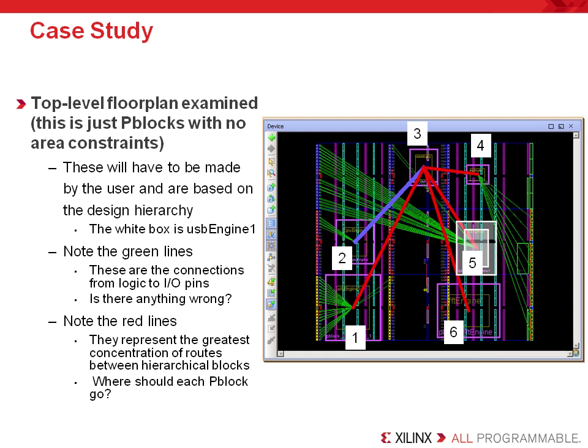Pblock 4 needs to be lower and closer to its I/O pins. Pblock 5 needs to be in the upper left corner of the die. This will put it near its I/O pins and next to Pblock 3. Pblock 6 could be placed anywhere, but it needs to be next to Pblock 3.